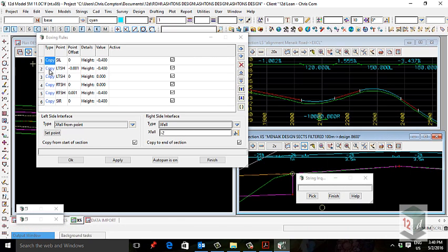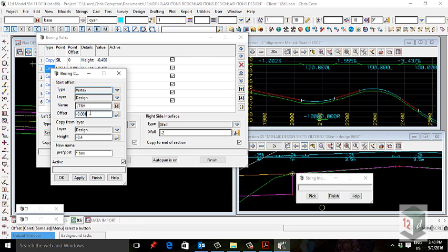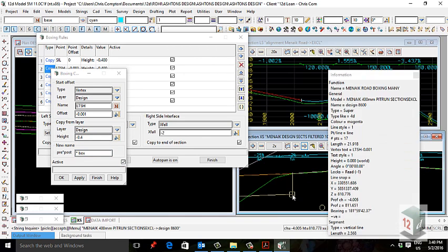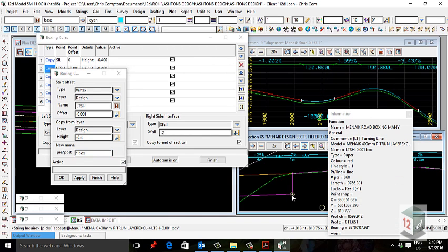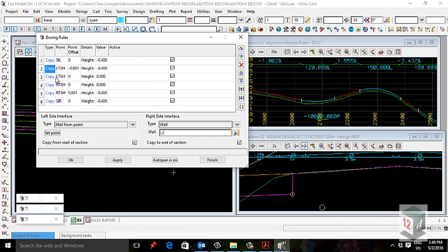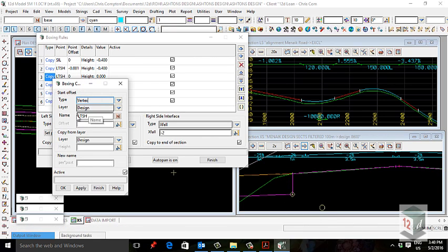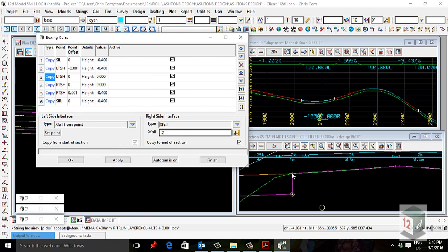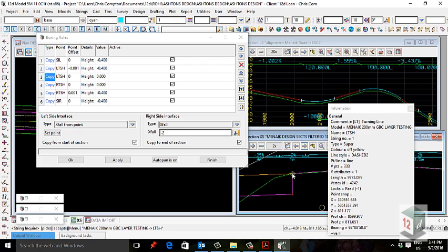We then go to the next point, which is this OG string, this LTSH string that we created, and I'm just offsetting it by like a mil, but I'm still dropping it by 400mm. I'm giving it a new name, so I'm calling it box, and you'll see a string created here called LTSH, using that -001 offset and putting a box name. I'm then going to the next string, and I'm copying LTSH with no offset and no height difference, so it's creating another string here called LTSH.